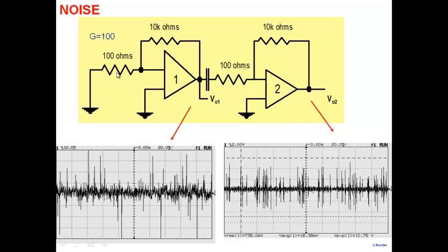All of these generate noise here, and then you see a certain amount of noise here, 10 millivolt. So this circuit is generating noise, which you see here. Now this circuit will also generate a noise of roughly the same order, let's say 10 millivolt. But this noise gets amplified by this one. And therefore, the noise that you observe at the output is the noise generated in this part of the circuit getting amplified by a factor of 100 and appearing over here.